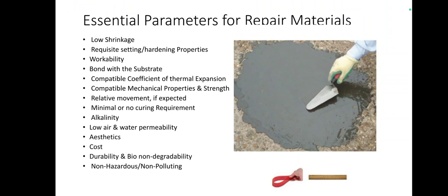In that case, I think for most of the roads, whatever repair they are doing, they won't do the curing at all. Once they finish it, they will allow some 6 to 8 hours to set, and then they will allow the traffic. Nowhere have I seen 7 days or 6 days of curing done. That itself is one of the bigger losses for retaining the strength, and also causes failure of this repair material.